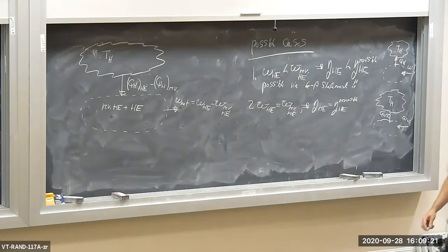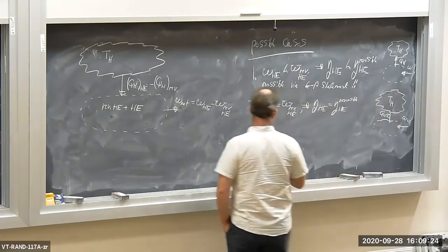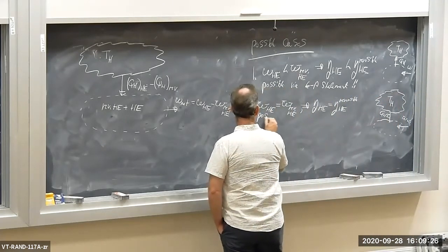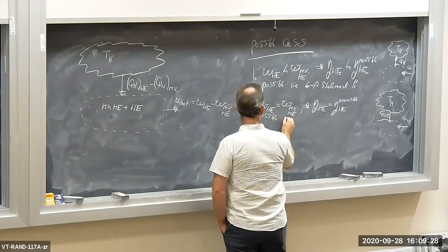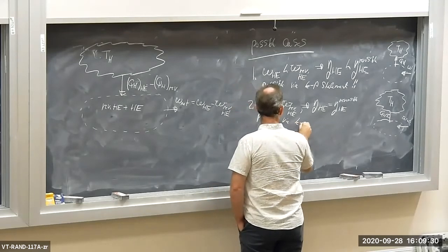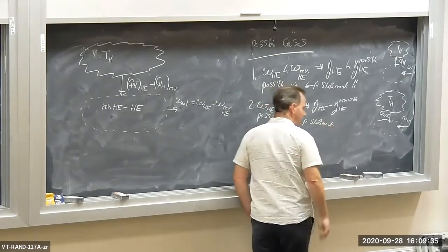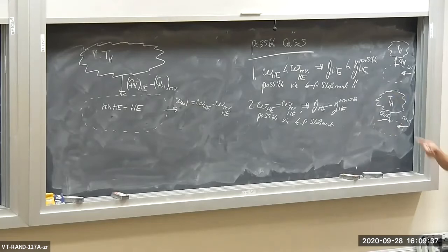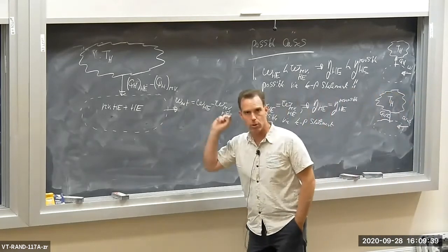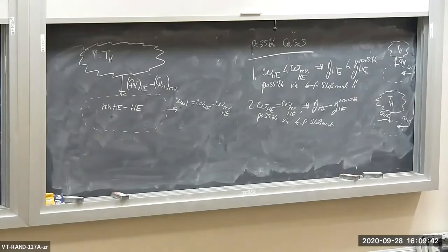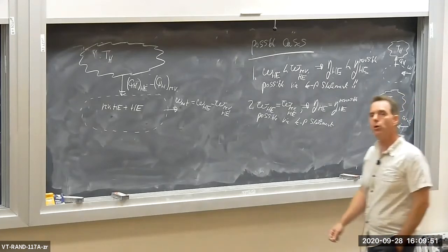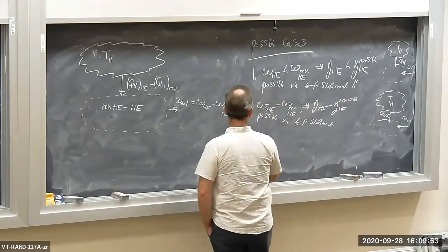This is possible according to the Kelvin-Planck statement. The Kelvin-Planck statement simply says that this device cannot produce work over the cycle. It doesn't say it can't consume it or it can't do nothing. It can do nothing, it can consume work, but it cannot produce it. Let's go to our final case.